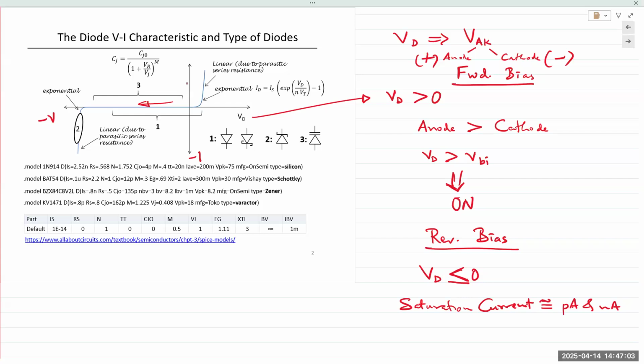If you take a straightforward connection where you're applying a sine wave or a square wave to a diode with positive at the anode, then the diode would be forward bias in the positive half cycle and would be reverse bias in the negative half cycle. So in the reverse bias, the diode must be able to withstand whatever voltage we're applying. Okay. Does that make sense to everyone? Right. So based on our application, a diode would be intentionally in reverse bias. Yes. Dan, you want to have a question? Okay. So that's one of the cases.